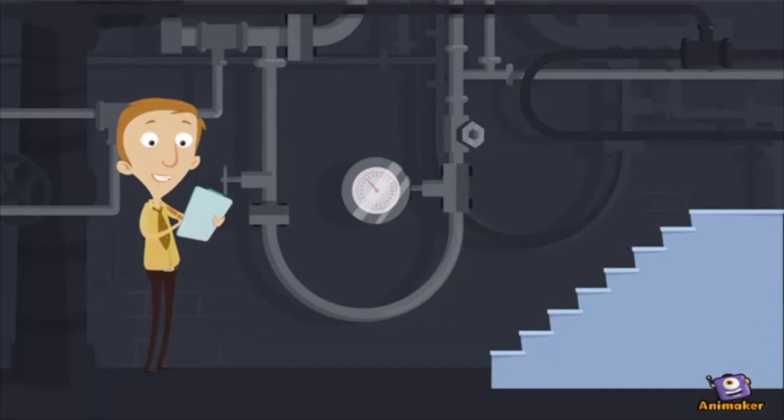An electricity plant equipped with pre- or post-combustion carbon capture technology will require between 10 to 40% more energy than one without it. This is energy needed to run the equipment to remove the CO2. Accounting for this increase means that the net amount of CO2 captured is approximately 80 to 90%. Alternatively, an Oxy Fuel system is able to capture almost 100% of the CO2, but the additional systems for removing nitrogen and sulfur lowers this value to roughly 90%.